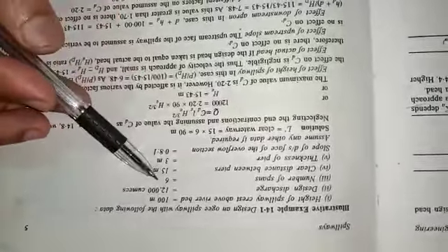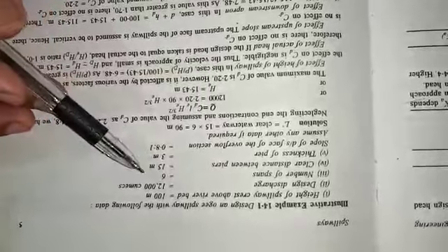Let us discuss a numerical example on the design of an ogee spillway profile with the data given. Here, the height of the spillway crest above the river bed is given as 100 meters. The design discharge is 12,000 cumecs. The number of spans of the spillway is 6.